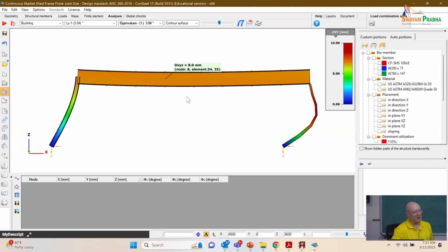We've basically got a problem, and this is what LeMessurier, when he was doing that inequality I showed you with the calculation of, what was it, the K factor. He would put a lower limit on the K factor because if he was looking at frames like this and saying, yeah, that stiffness-based model that we use, that's just a side sway stiffness model, it stops working so well when we get to a frame that's like this. Let's be careful.